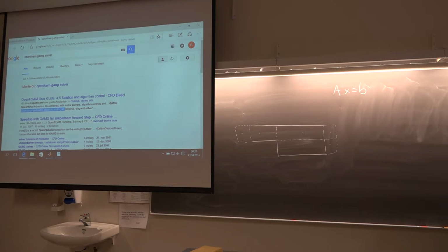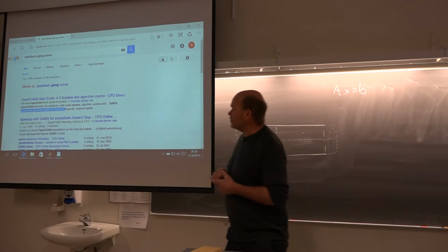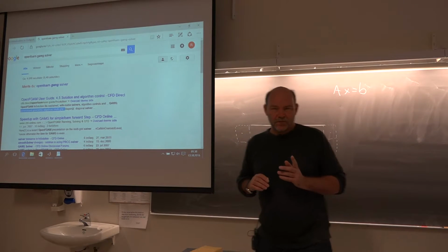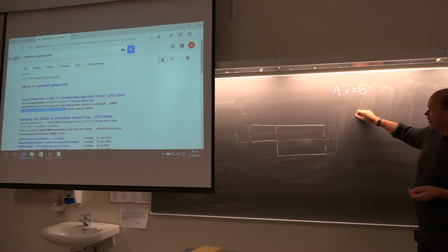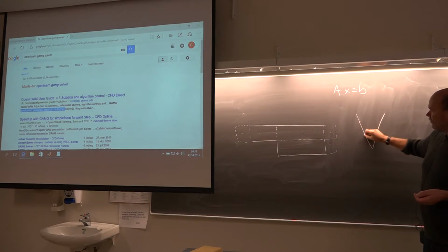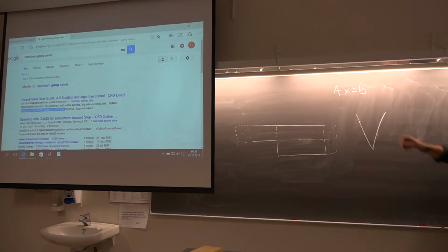Still, you risk having to find the input values into these routines. Some questions that you then may have to answer, like should we use a V-cycle, that goes down to the coarsest mesh and goes up again? Should we use W cycles? What's that? Well, then you have other options. You don't go directly up again.